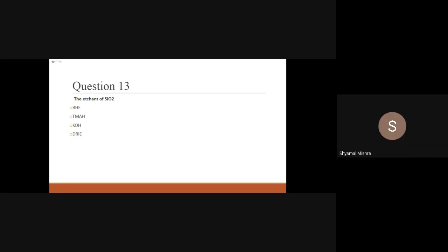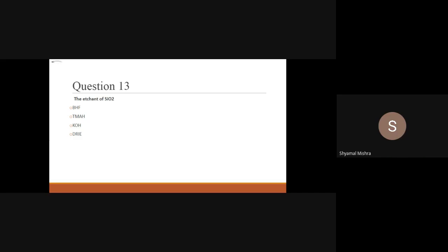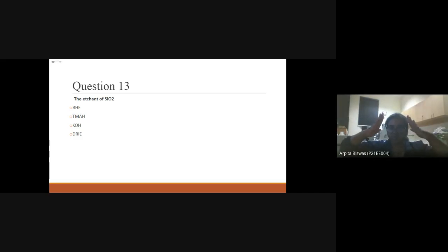Okay. And in the etching process, the angle between the 100 and 111 planes is 54.7 degrees. That's why this type of shape is present when we fabricate the pressure sensor. We want to make a diaphragm type structure. So in that case, the angle between the 100 and 111 planes is 54.7 degrees.